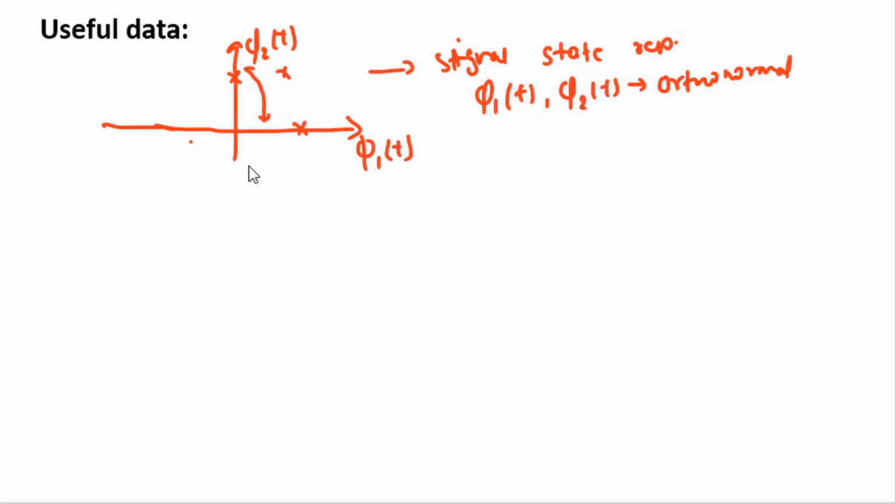So the probability of error will be decided by the distance between these two bits, that is d min. So you need to remember that probability of error is dependent on d min. If you increase this d min, then the probability of error will decrease, because the two bits are separated by a much larger distance.